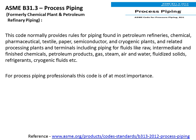Next is ASME B31.3. It was formerly called chemical plant and petroleum refinery piping. This code provides rules for piping found in petroleum refineries, chemical, pharmaceutical, textile, paper, semiconductor, and cryogenic plants and related processing plants and terminals, including piping for fluids like raw, intermediate, and finished chemicals, petroleum products, gas, steam, air, and water, fluidized solids, refrigerants, cryogenic fluids, etc. For process piping professionals, this code is of utmost importance.